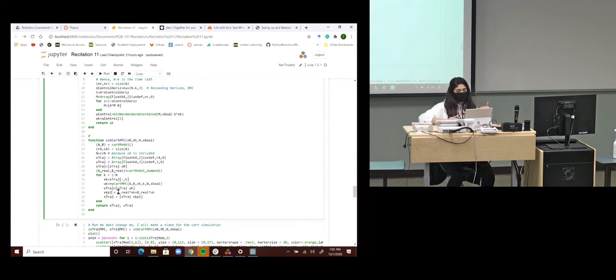I keep doing that, but you have to note that at each time instant, I'm measuring where I am, then I'm planning for a particular time horizon, then I execute my control for that time instant, and then at the next discrete time instant, I again note where I am and then replan, and then execute, and then replan.